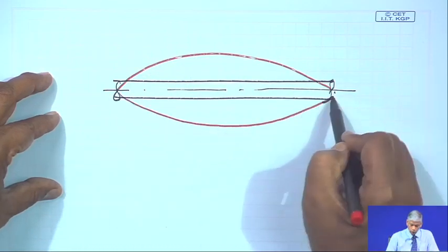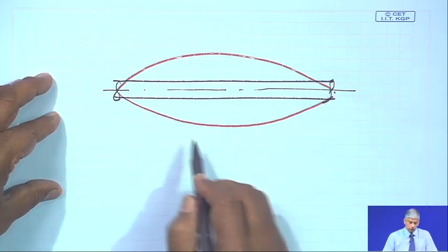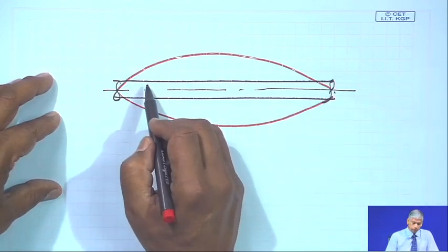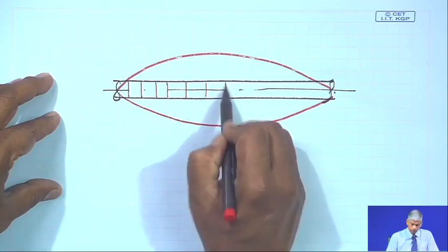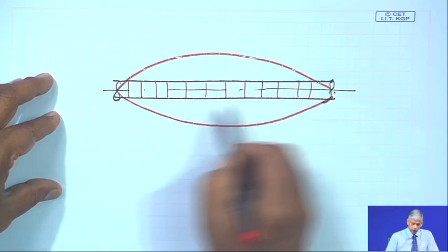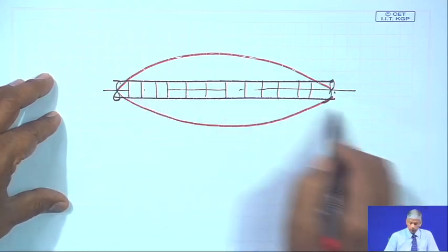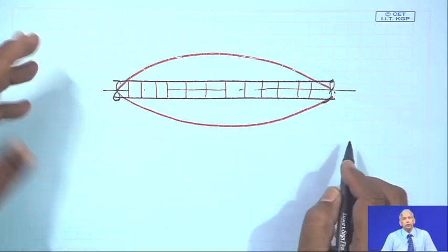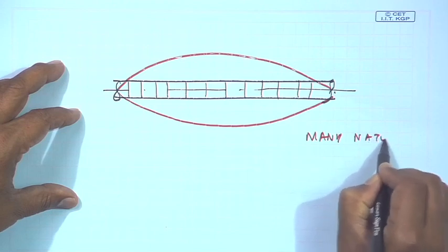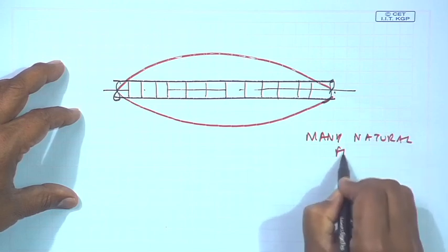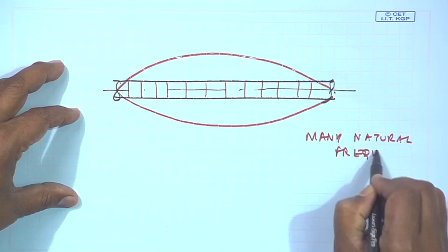While rotating, they will bow out. Okay. Now, the question is, because I could divide this shaft into many degrees of freedom, I can have, theoretically speaking, an infinite degrees of freedom system, but within a limited range there will be many natural frequencies of this shaft.